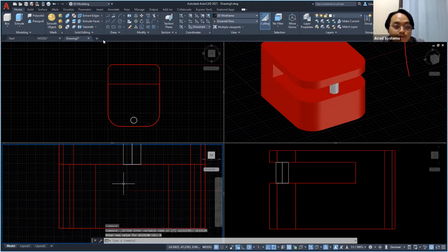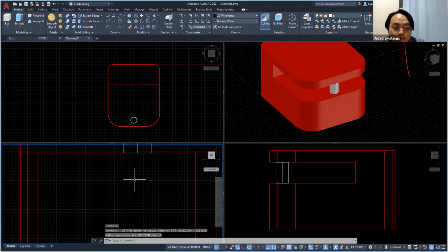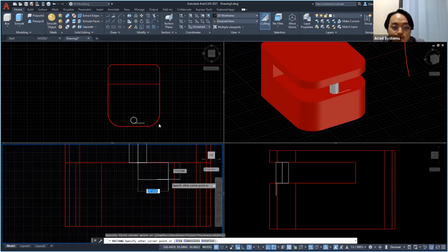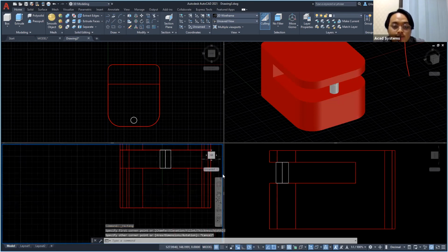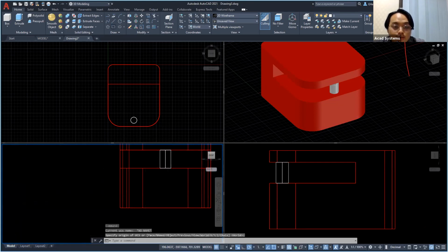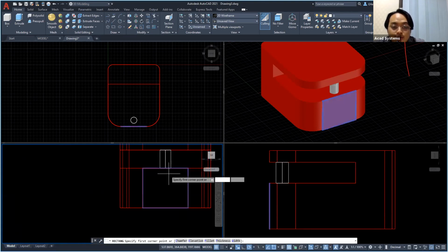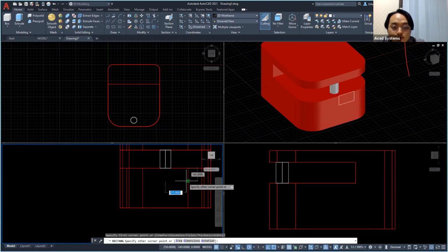What I will do now is draw a box here. Notice that the box we draw is at the circle here, at the cylinder, at the arms. And what if we did not change the plane? I'll show you what happened. This is because we have our snap dynamic UCS, so we can automatically snap onto this. We want to create it 200 and also 10.